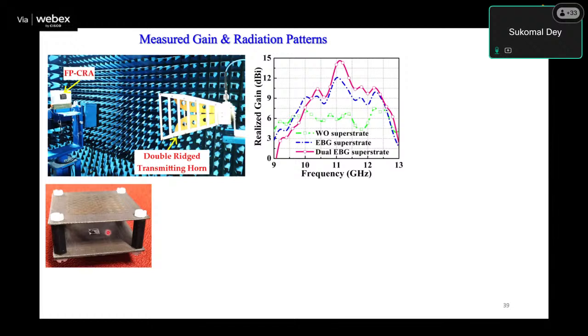Now the antenna, forget about getting a gain like this, close to 14 dB or 15 dB, from a single patch. Here there is no novelty on the antenna design, but there is something on the other side of the story, like on the peripheral. You are adding more peripherals to the design to improve the performance. When you do not have any constraint in terms of size, this concept cannot be blindly adapted everywhere. You can only use this concept for military and space applications.